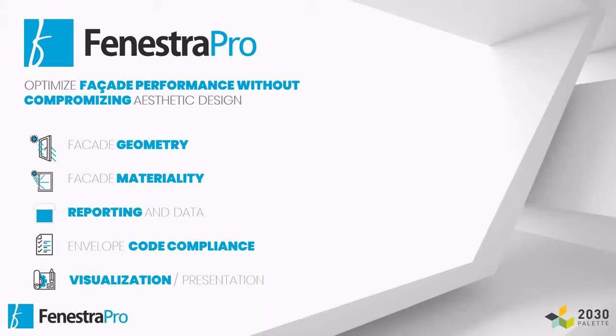In other words, how much glazing versus wall I have, where that glazing is situated, whether there's shading included, what that shading will do, and materiality: what type of glazing am I using, what type of performances and properties that glass has. There's a good element of reporting and data so we can drive decisions and justify our decisions. Code compliance and some of the parameters around prescriptive performances or window to wall ratio are very much to the fore, so we can make decisions within those limitations that codes might restrict us to. And visualization and presentation, we can see what those performances look like, and we can see where they're applied to.